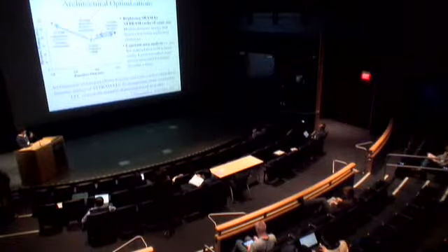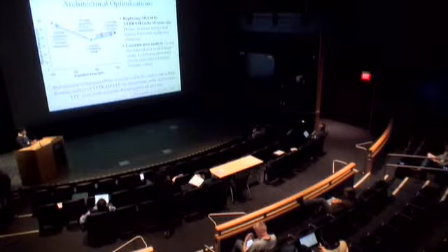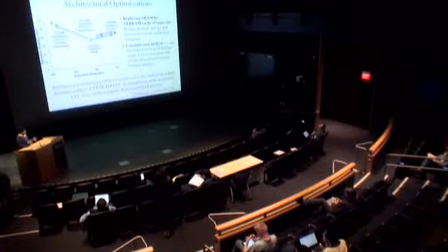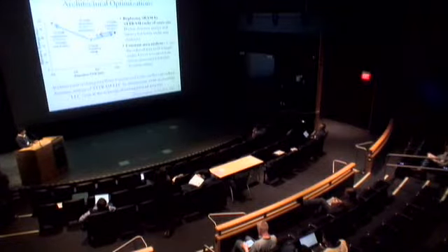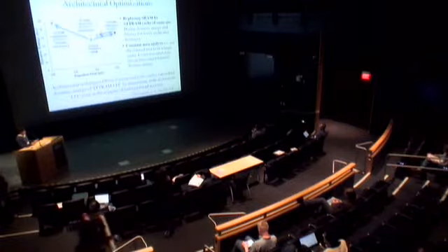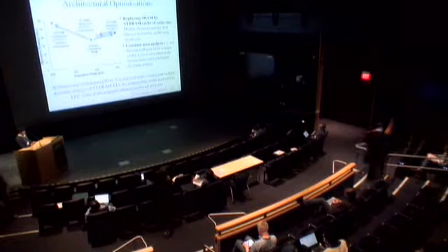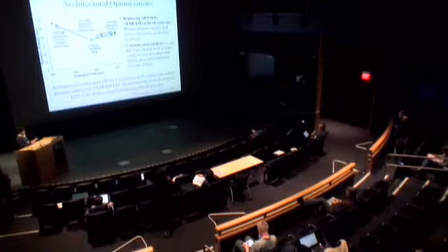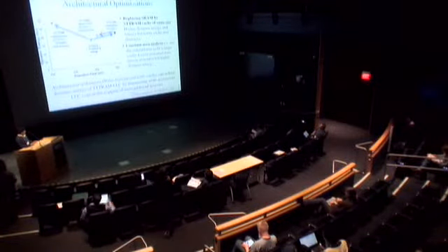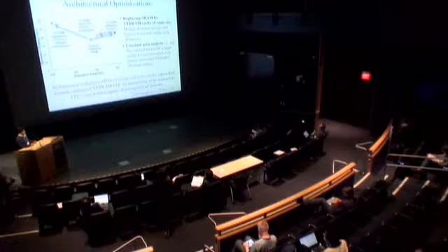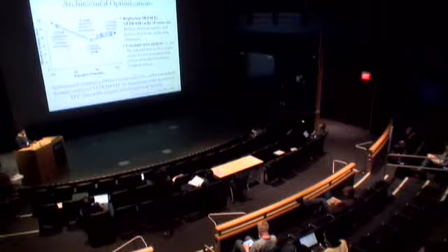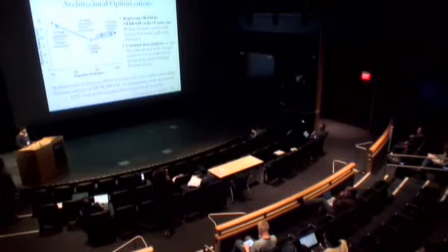So I can tell you this much: we were trying to use STT-RAM LLCs, and we had a cache by means of which we were trying to filter out some of the writes which were going into the STT-RAM LLC. Now that involved some other techniques as well, which had to do with the kind of policies you would adopt for eviction and all that. But I guess you could have a look at the paper, which discusses all of that in detail.